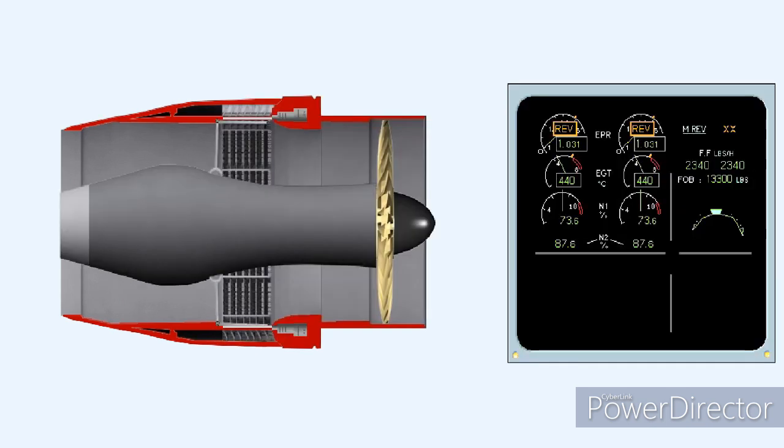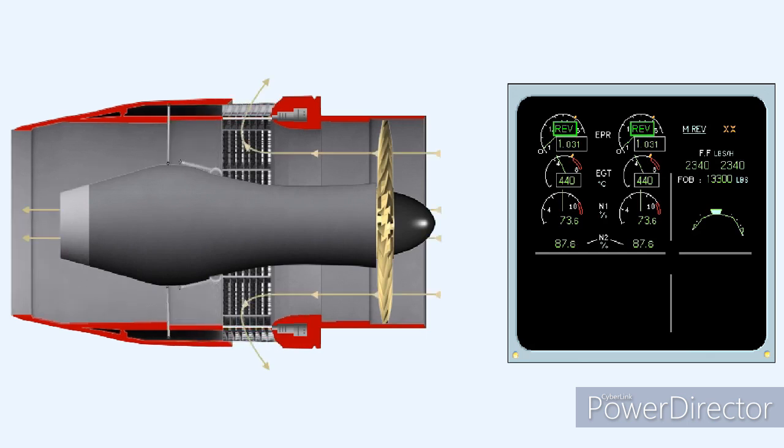In order that the pilot may have information regarding the position of the reverser doors, some form of warning is fitted. The warning can be amber lights positioned somewhere on the forward instrument array within full view of the crew, or, as is shown here, captions which appear on the electronic centralized aircraft monitoring system. The warnings will be shown whenever the reverser doors are unlocked and away from their stowed, forward thrust position.